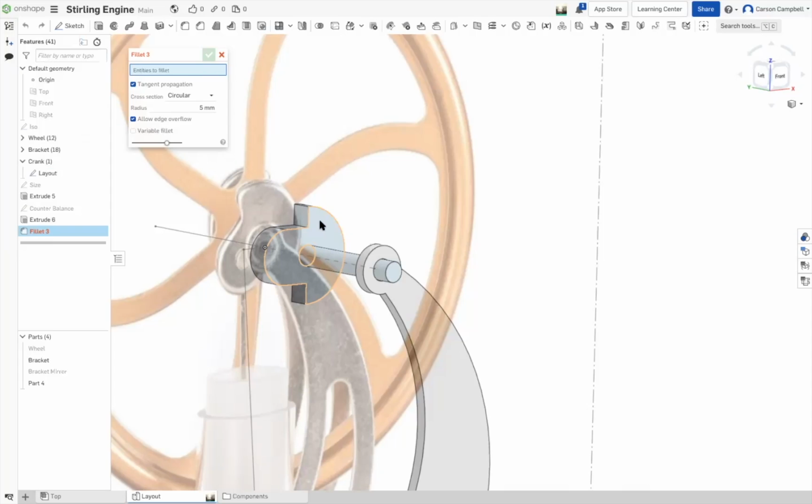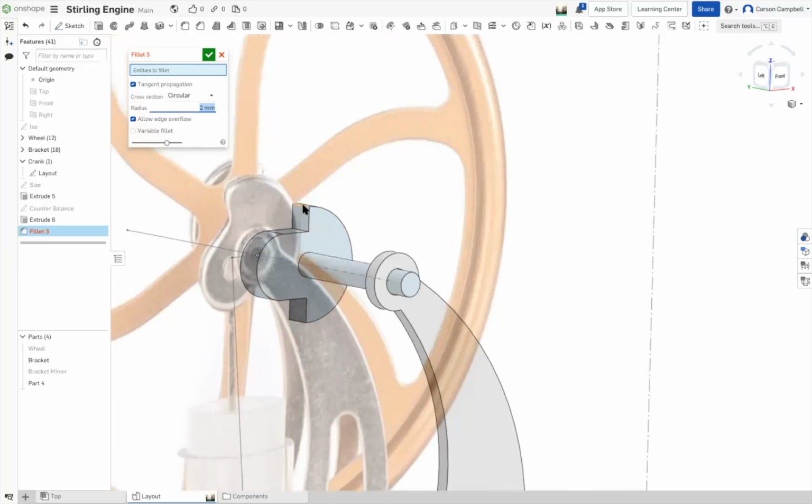So, and after all, designing is all about the next guy. It's not about you. Go ahead, change your dimension to 2 for your radius and go ahead and click those 4 edges. Can I do a surface? No, you can't. You got to pick the 4 individual edges. Pick, and then change it to 1, possibly change it to half. Yeah, let's go half.